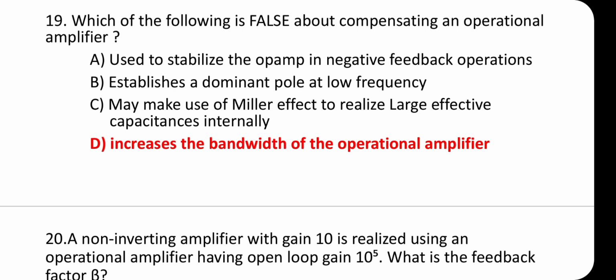A practical op-amp is frequency dependent with many transistors and junction capacitors. If such an op-amp is used as a buffer, the output is fed back to the input and subtracted. Subtracting means 180-degree phase shift. For a circuit of order 3 or higher, the delay offered by the circuit for a particular frequency is an additional 180 degrees. The circuit will oscillate at this frequency and the system is said to be unstable. Frequency compensation is a technique used to solve this problem.